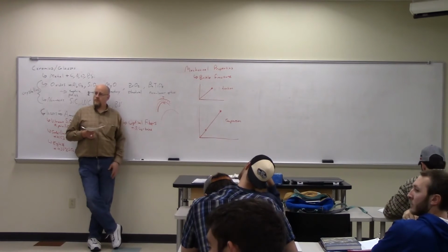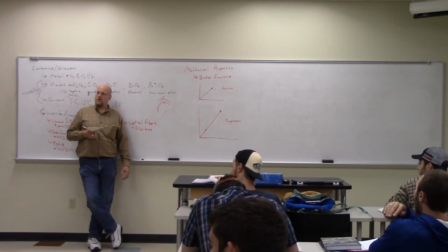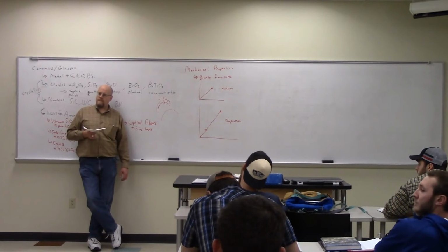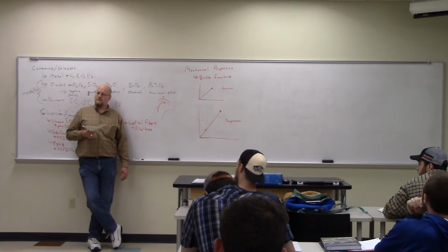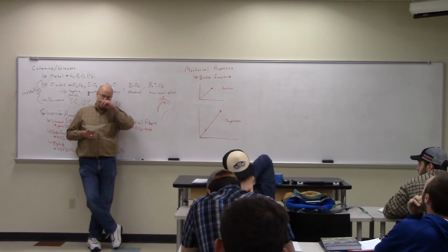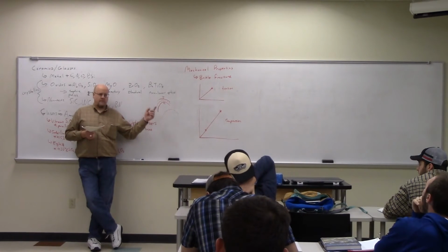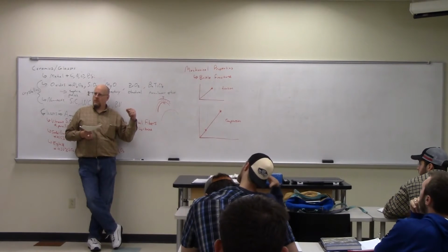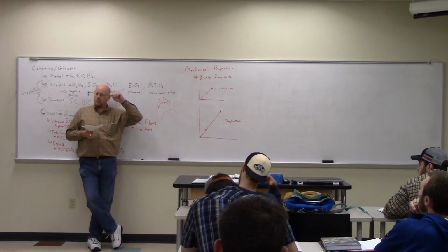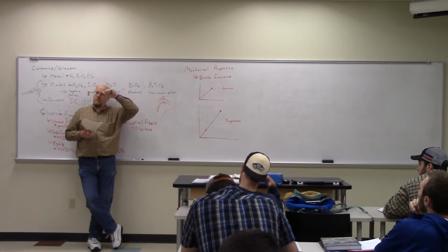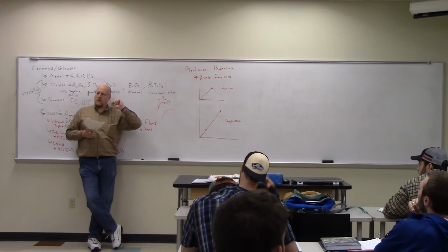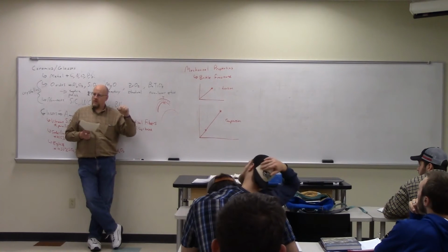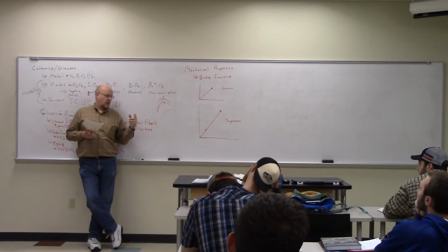But you could bend it enough to shatter it? Yeah, you can snap it. Can you do that with soda lime silica glass? Could you make it thin enough? Sure. I don't know if you've ever worked with microscope cover slips. Those are generic soda lime glass, and you can bend them. You can't bend them in a radius this big, but you can bend them without breaking them.